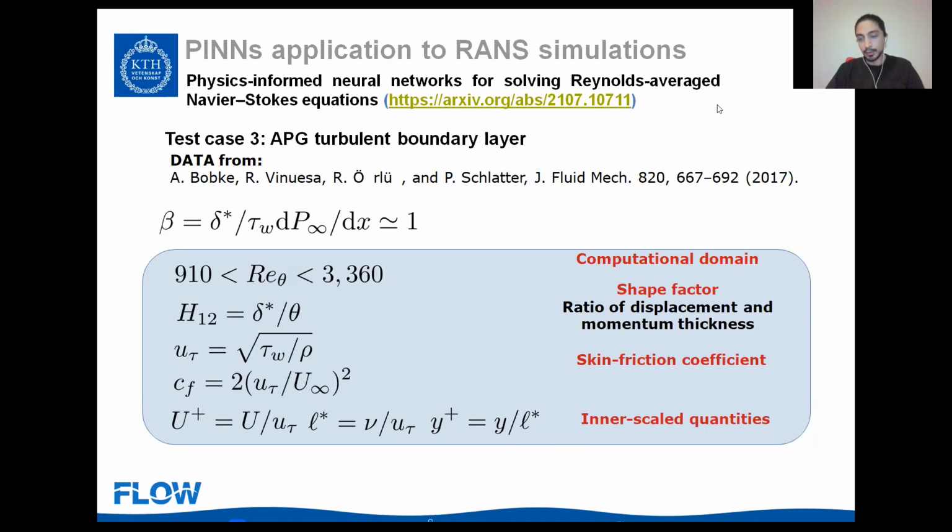Of course, it would be dependent, because that data guides the framework to the actual solution. So the quality of the data is important. In this case, we used DNS data averaged through time, or well-resolved LES, again averaged through time. So the statistics of those high-fidelity simulations.